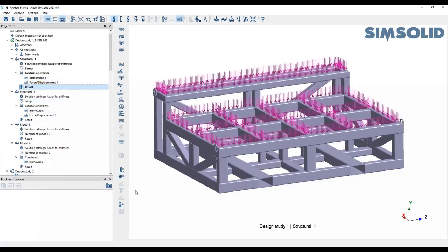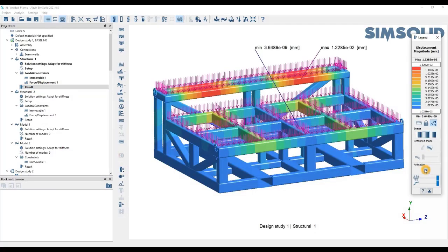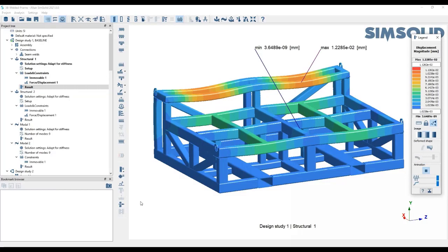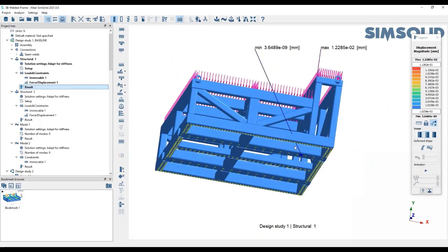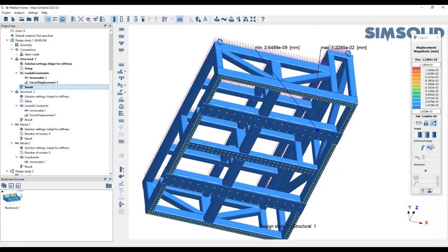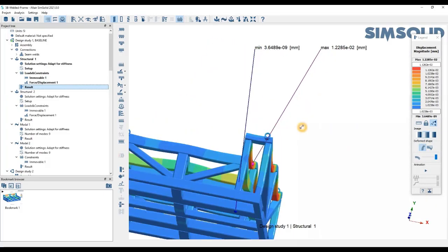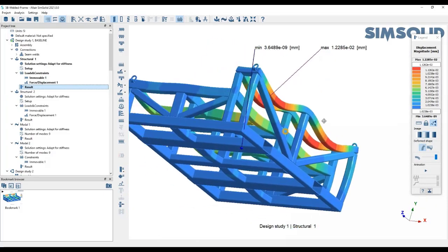And last but not least, I'm just going to show you the quick processing of this as well. When you have a moving animation, just click on the camera icon, and because it's moving, it knows to save it automatically as a video. Let's say we're actually looking at, let's make this a bit more dramatic in terms of the scale deformation, and let's say this is the angle that we care about.